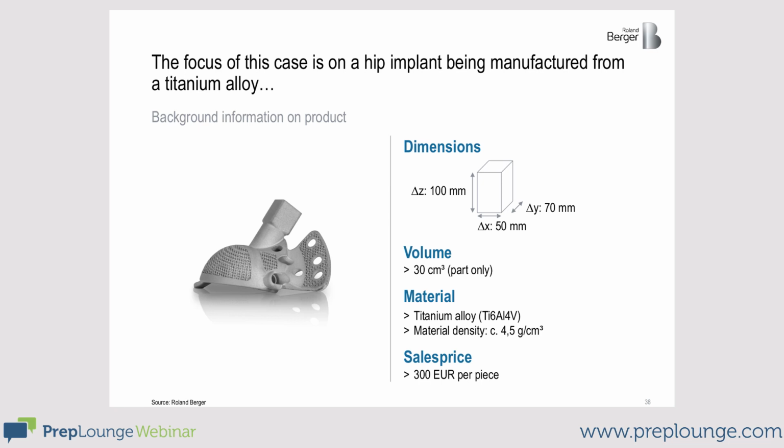One possible question for the case could be, how can I determine the volume when I only have the piece lying in front of me and other than that, no information at all? A good approach would be to use the displacement principle. You could put the piece in a measuring cup and measure how much the fill level of the cup differs. Most of the time that works pretty well.